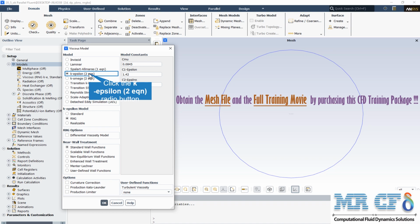The RNG-based K-epsilon turbulence model is derived from the instantaneous Navier-Stokes equation using a mathematical technique called renormalization group, or RNG method. The analytical derivation results in a model with constants different from those in the standard K-epsilon model, and additional terms and functions in the transport equation for K and epsilon. The K-epsilon RNG turbulence model is used to model transient flows in geometries with high curvatures and air conditioning problems.